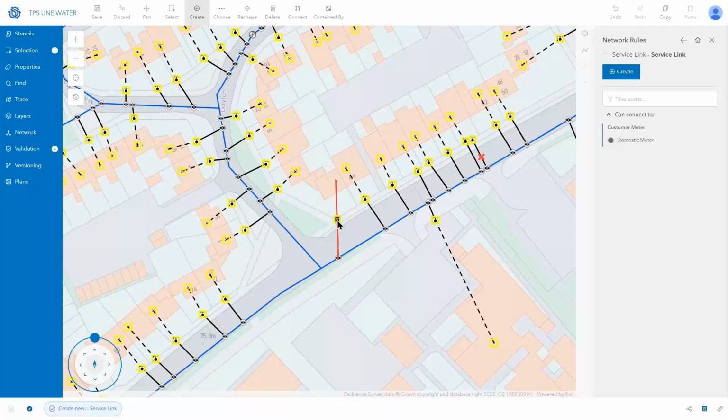And we can see this time, a quick look at some of those COGO tools. So if I wanted to limit the segment to 15 meters, you can see when I do that, it's not going to draw any further than 15 meters. And if I wanted to, I could do the same for the angle or draw an offset of that line as well. For now, I'll just complete that.